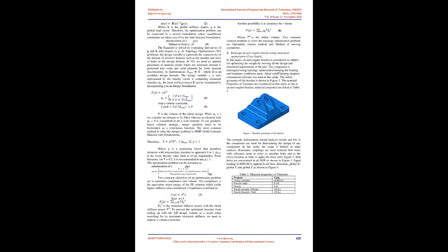For example, the aircraft engine's design requires that maximum reliability, minimum materials consumption and maximum payload volume, or load lifting capacity, be provided simultaneously. Topology and shape optimization techniques are very useful in the early stage of development of any aero engine part, as it reduces the number of iterations and ultimately reduces the time to market and cost of the part. The parameters like thickness and radius are reduced by applying shape optimization on a structure.